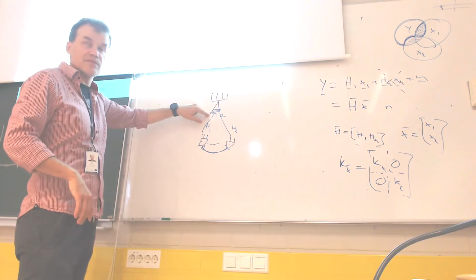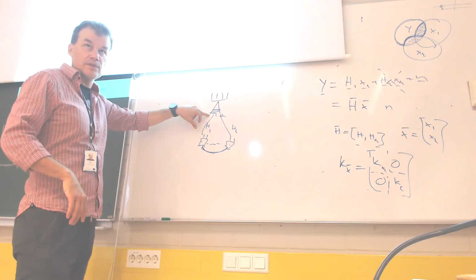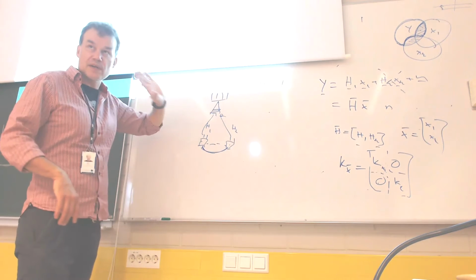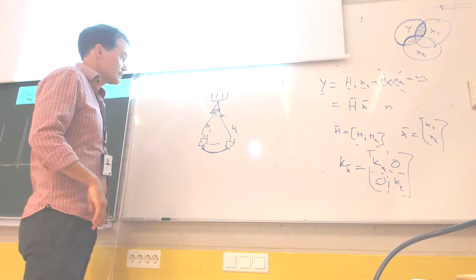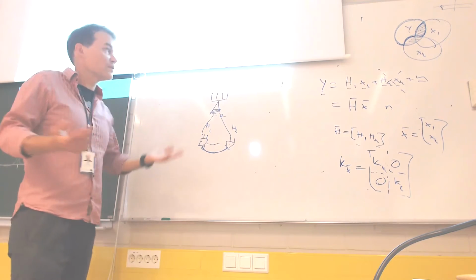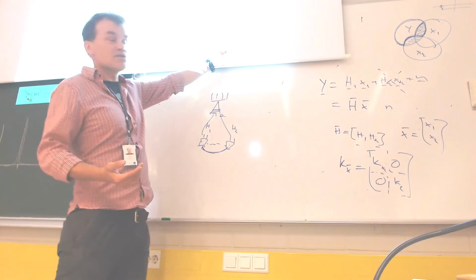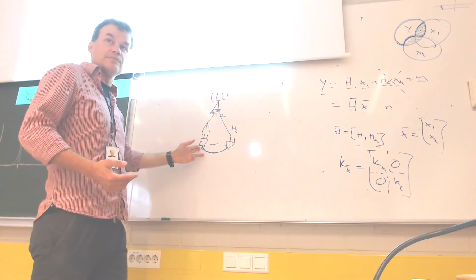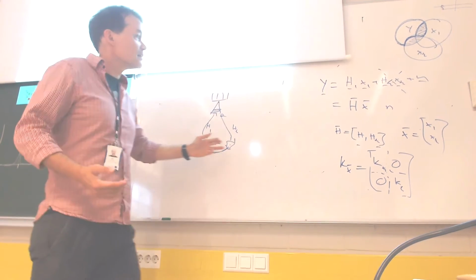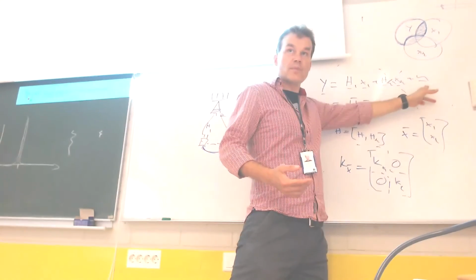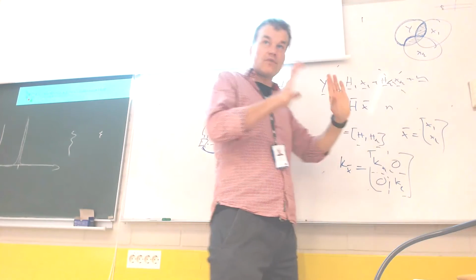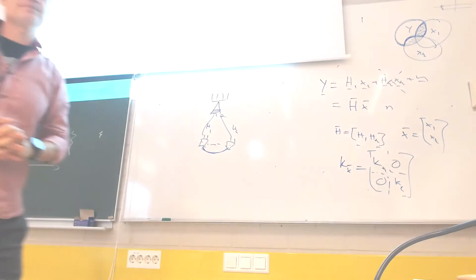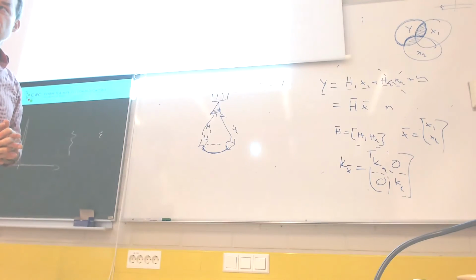This P is the received power. You can also include the path loss in the channel itself, and then use the actual transmit power and the actual thermal noise level, and everything holds. It's all relative. The SNR is the same. Makes sense?